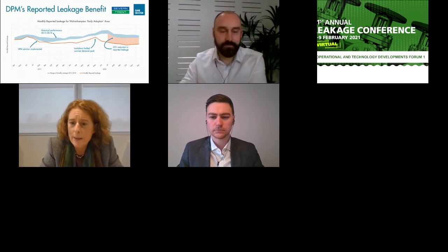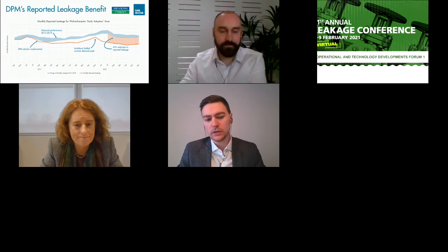Adam Stewart, DPM seems an ideal solution for burst awareness. In DMAs where you have deployed DPM rather than acoustic technology, how have you tackled reducing existing leakage levels? So with DPM, we know that it wouldn't necessarily pick up the low-level, incremental bursts. We knew that it was going to help us when we got DMAs low to keep them low.